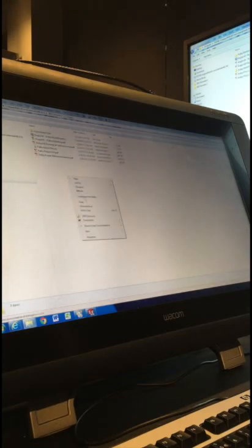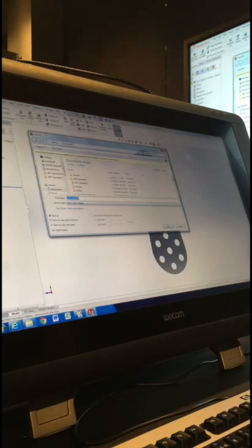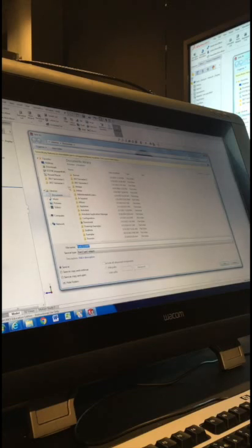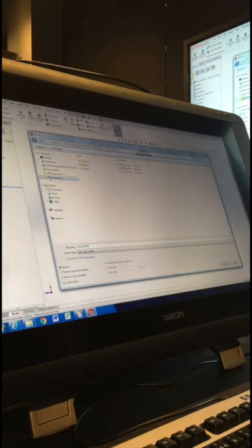So you can create your own folder on there. I suggest you do. So create a folder, CAD to CAM, create another folder, project 1, and then save your parts in that folder. So I'm gonna go and do the same thing. Class files. Again, name it whatever you want, but I'm just creating that folder there so that now I can save my part. Project 1, class files, you go PO3, and this box that says description at the bottom, that's where I'm putting in side plate. Save.